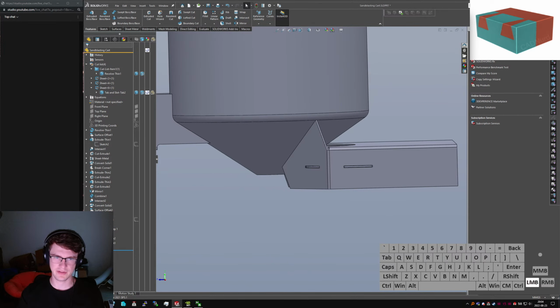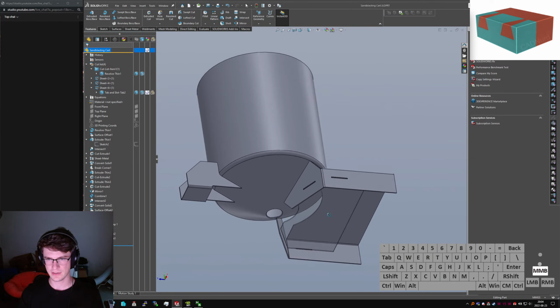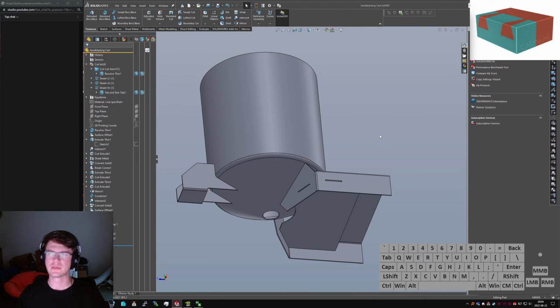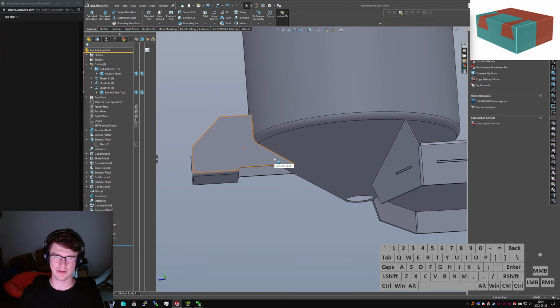Yeah, I don't think I really have anything else clever to say besides that. Use tab and slots; they're great, especially if you're welding together assemblies that are tricky to fit together. It saves your welders on fit up. It just makes fitting things together and requires a lot less jigging if you have tab and slot all over the place. I think I did this once with a 5-foot long aluminum beam that I was building that had all sorts of complicated internal webbing, and I'm told the welders hated me slightly less for using tab and slot. It made things a lot easier for them, so consider it if you're designing parts like that. It's not really useful otherwise. Maybe you could do it on 3D printing, but it just means tweaking your tolerances, so.